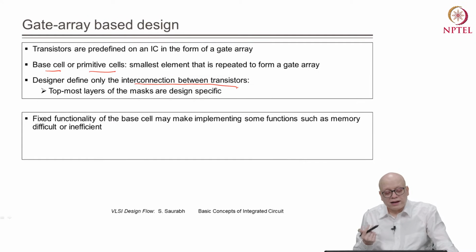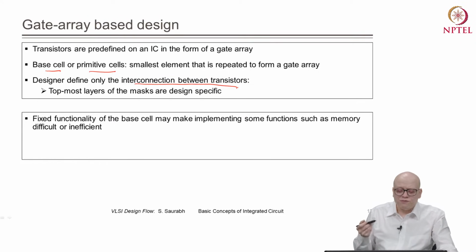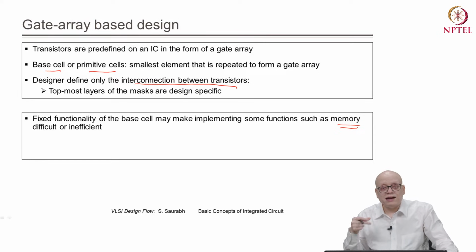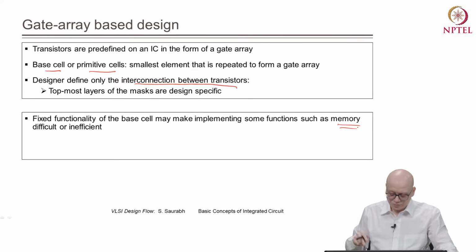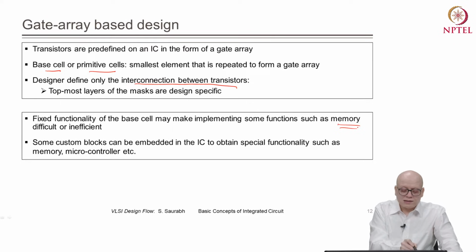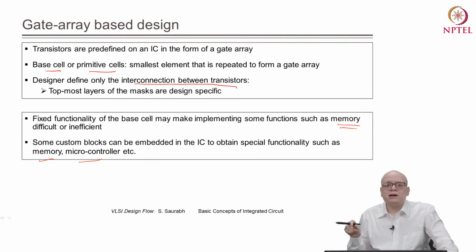So for gate array based design, realizing some functionality, for example memory, can be very difficult. Why? Because we have only a primitive cell and we have to design everything in terms of primitive cells. However, the vendor of gate array based design may have products in which memories, microcontrollers, etc. are pre-embedded in your layout, and those can be reused for obtaining the functionality.